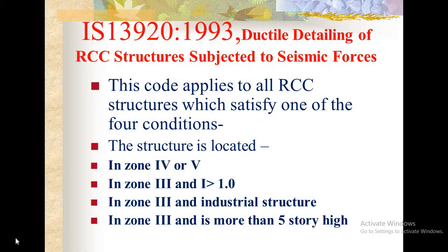The lateral reinforcement tends to improve ductility by preventing shear failure, and bond failure and anchorage failure are sudden and brittle. Special attention may be given to these details.